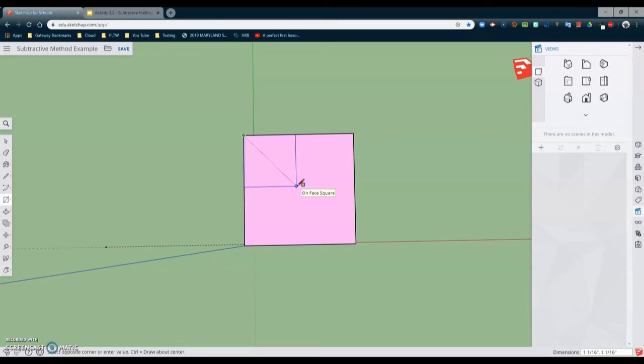And these go in a little bit different than your normal line tool dimensions would go in. We're going to need to have a length and a width for our rectangle. So we're going to go ahead and add our 0.75, which will be our length. We'll add a comma and then add the width of this, which will be another 0.75. Once we go ahead and hit enter, it will lock into place for us.